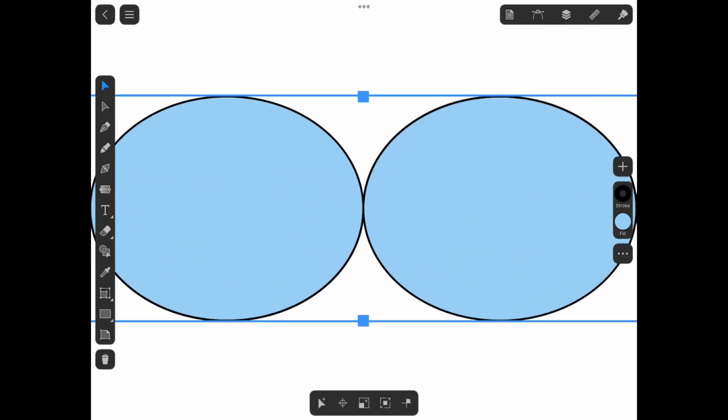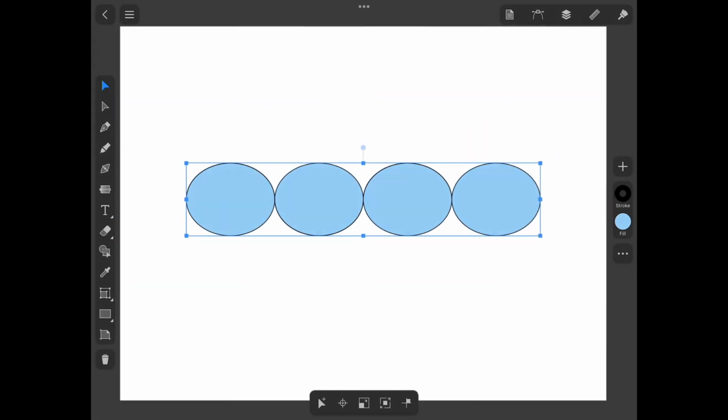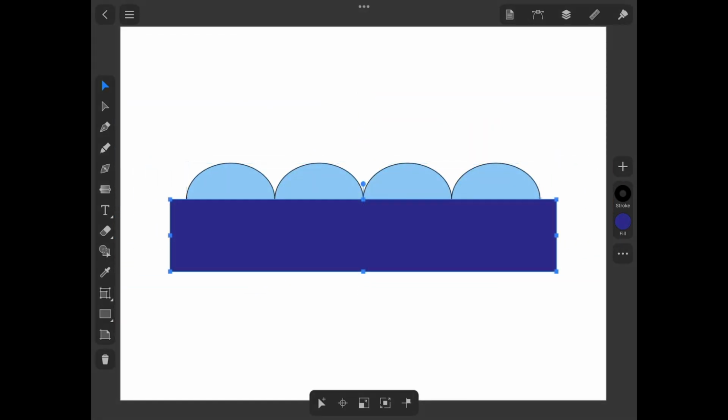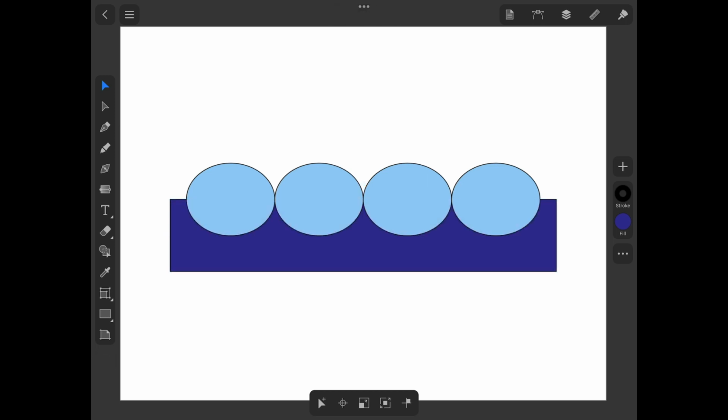There's another important rule. The Fusion tool works with closed shapes, and the shapes must overlap. So we have to add a rectangle that will serve as the body for a shape whose top will be wavy. We'll delete it later. The Fusion tool can edit only objects that are selected. In this way, we select the ovals and rectangle and then activate the Fusion tool.